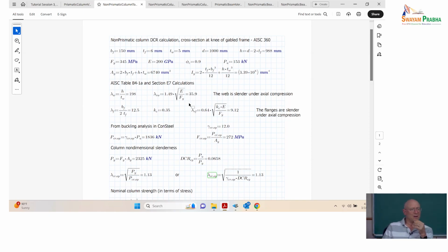The idea is, suppose that you are doing a buckling analysis to verify your design on some structure that had several columns. Now, if you apply the load, you do the buckling analysis, you can say, well, what's the load in each of those columns at buckling, right? That's your P critical or your PE, if you like, okay? All right, and then you'd say, okay, now I'm ready to check each of those columns.